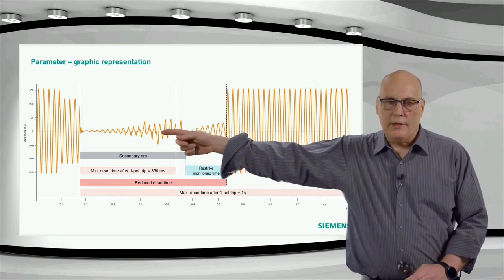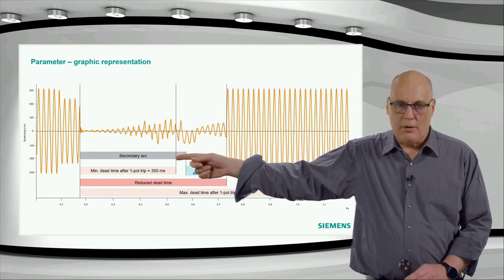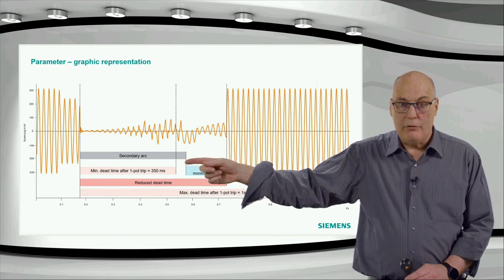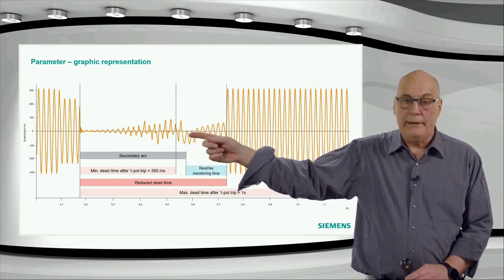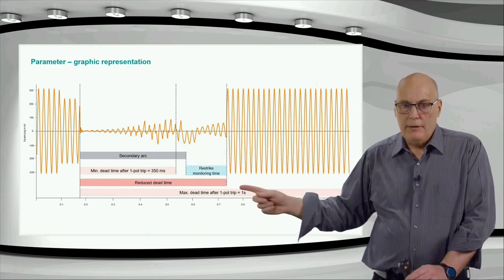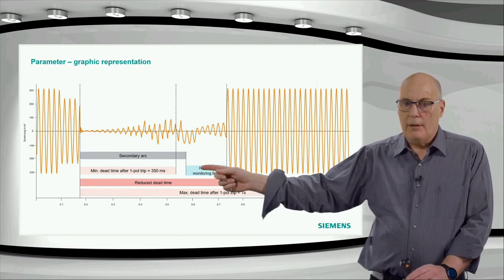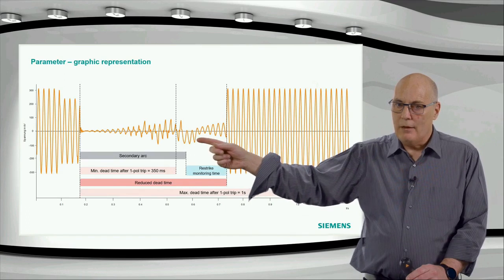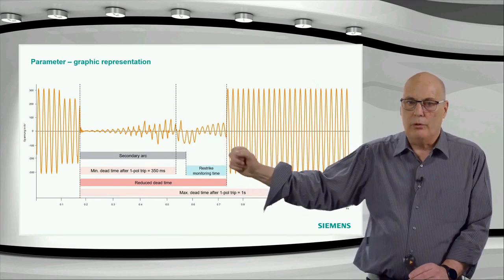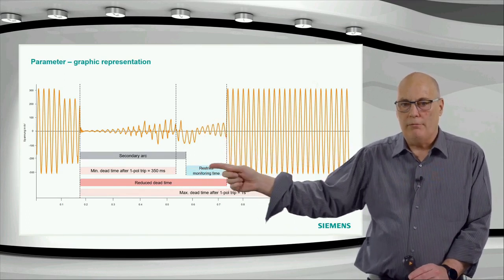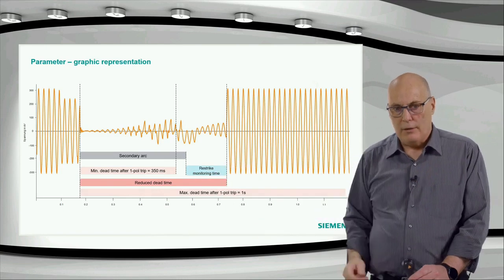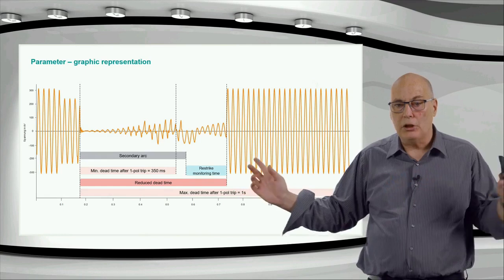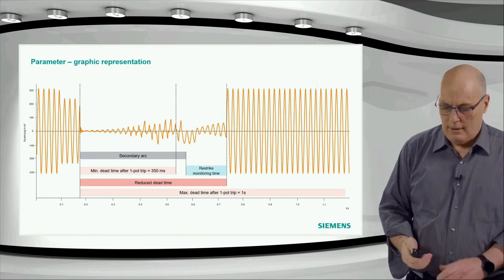And we detect the secondary arc. You can see the alarm up, secondary arc detected. When the secondary arc disappears, you can, in theory, permit closure immediately. There is a stability time, a so-called restrike timer, just to put it. Could be that it disappears and then it restrikes here, then you don't want to release the close. So you have a monitoring time, 150 millisecond restrike monitoring time. After that, the closure is then released. You can have a much shorter dead time in this technique.